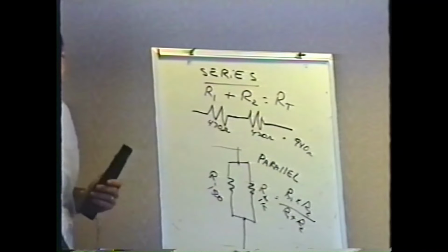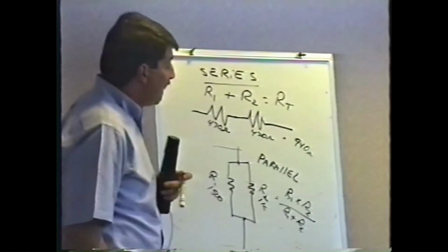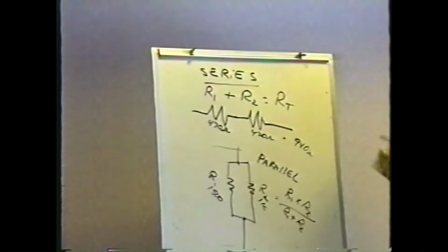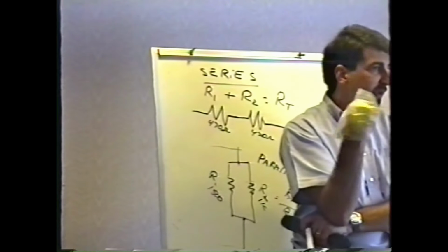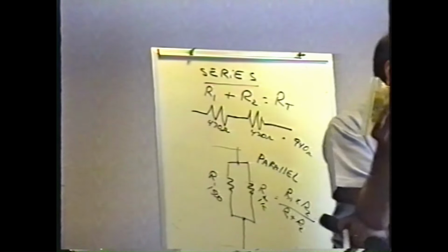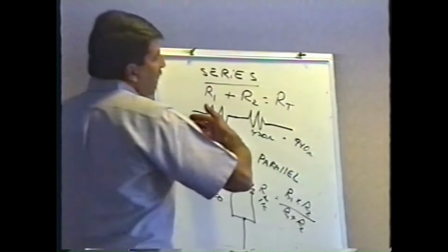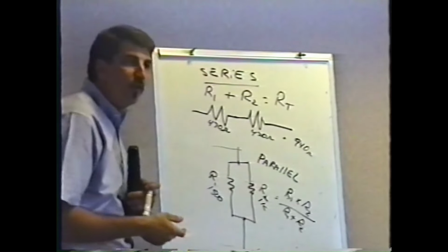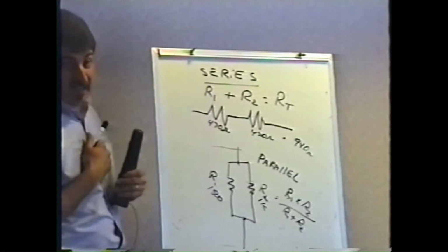You could do this. I've done this more than once. And I'll show you later on with something called a capacitor, where you really sometimes need to do this too. But quite honestly, since resistor failures are so rare, and a bag of resistors like this costs you a couple of dollars, even from Radio Shack, there's no reason why you shouldn't be able to come up with the correct value resistor, to be honest with you. But as far as simple work like that is concerned, putting them in series adds them up. Putting them in parallel, if you just always make a point of using the same value and put them in parallel.